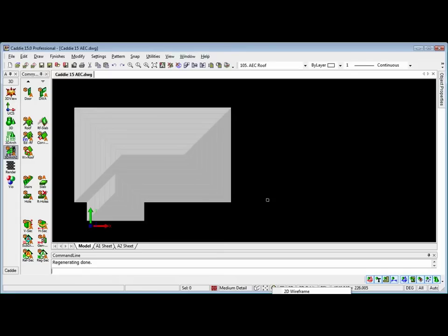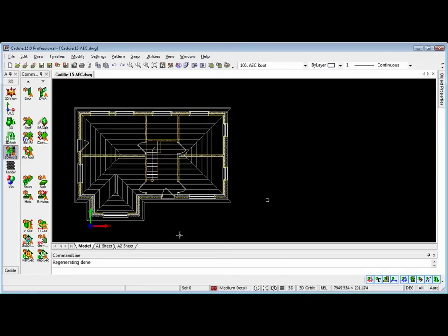Choosing a wireframe representation for our model rather than the shaded view, we can see again the stairs and the layout for our drawing underneath. So let's take a look at what a vertical section might appear like. Vertical section, quick section, and we'll take it so that it will run through our stairs and through the window beyond. Looking in that direction, let's place our section there.